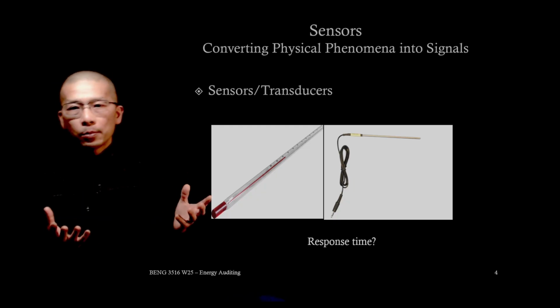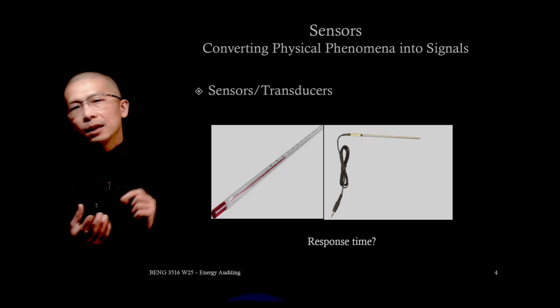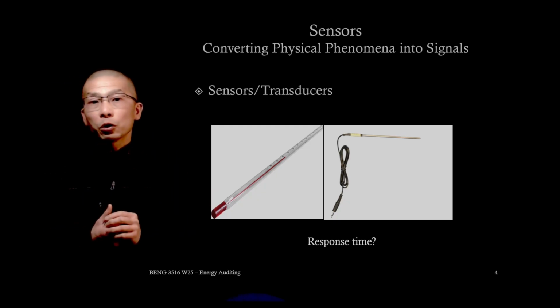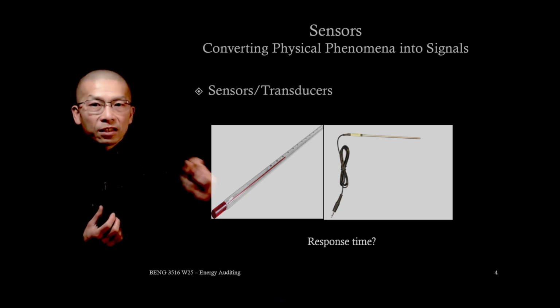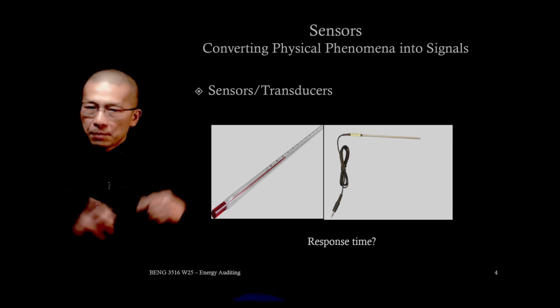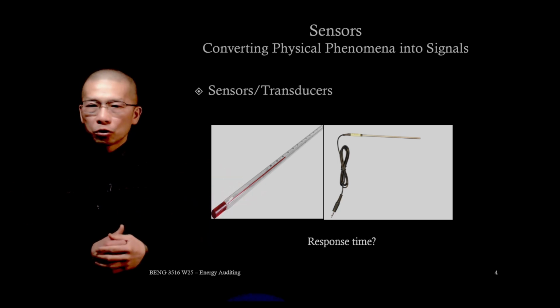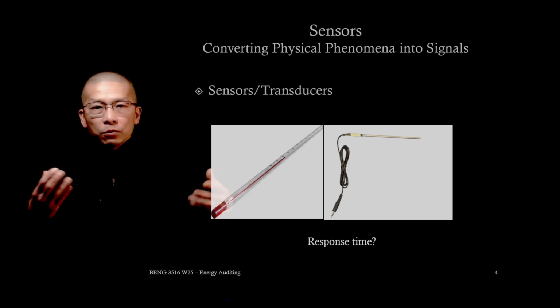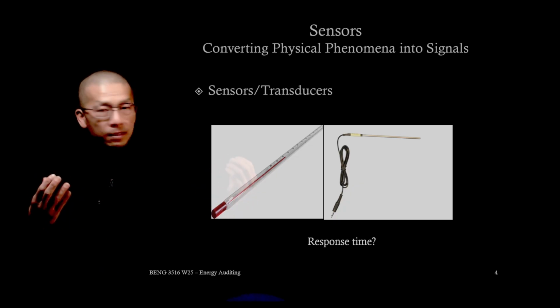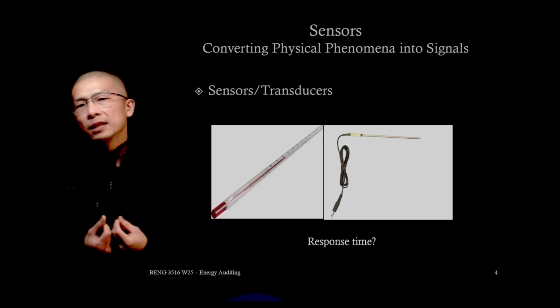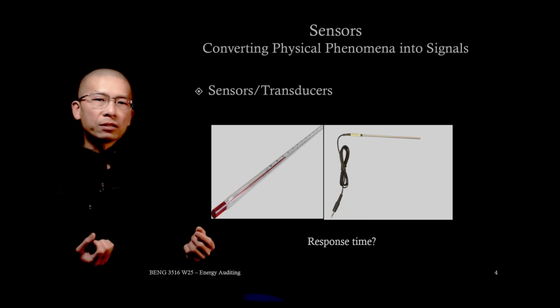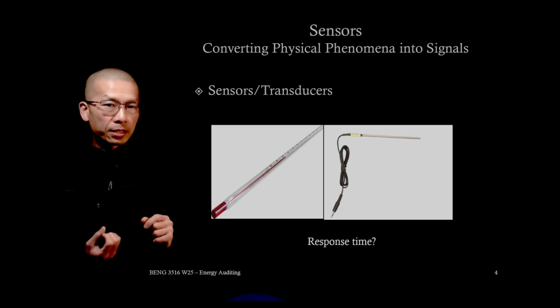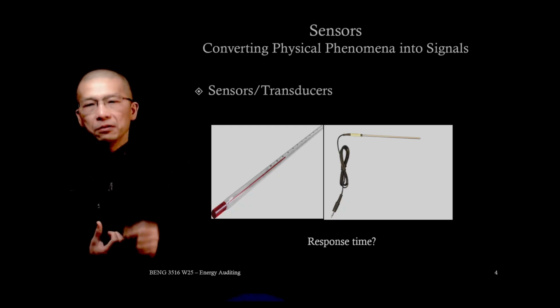The thermocouple produces a tiny millivolt signal that requires signal conditioning, maybe amplification or transmitters, to make the signal readable. In short, sensors sense changes and transducers convert them into readable signals.